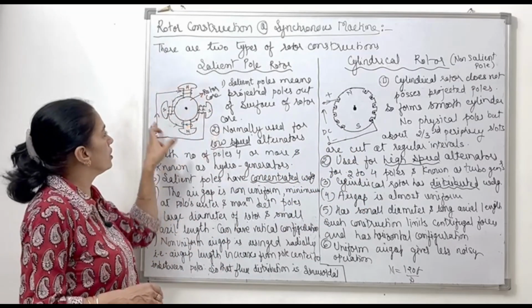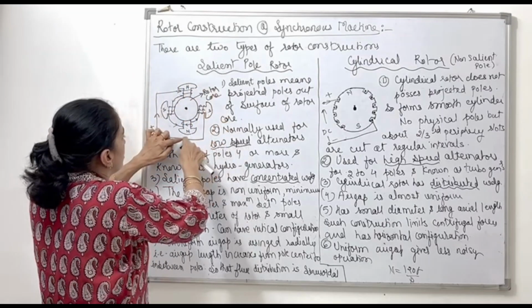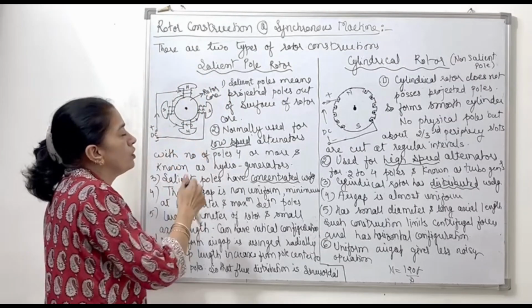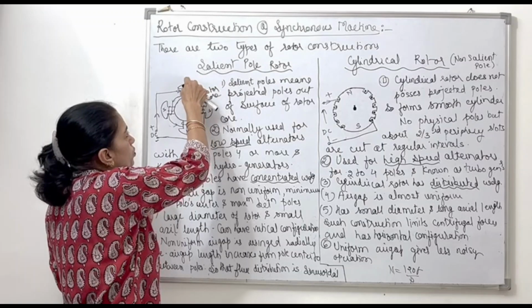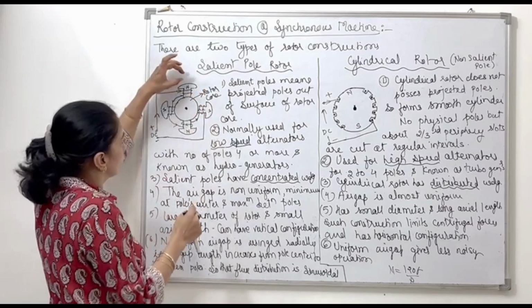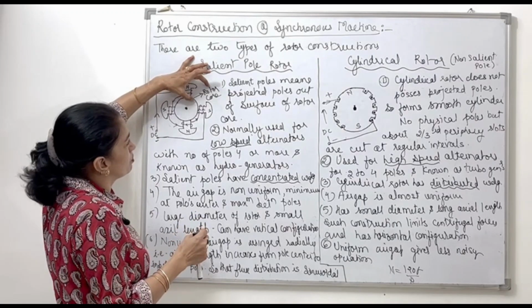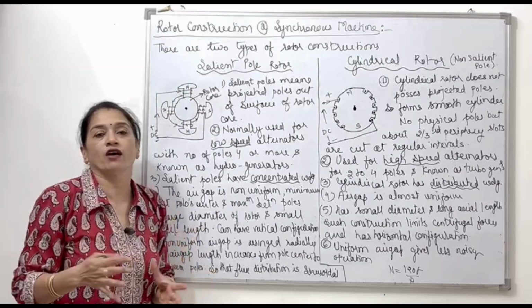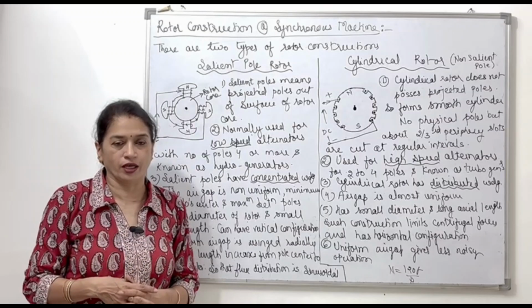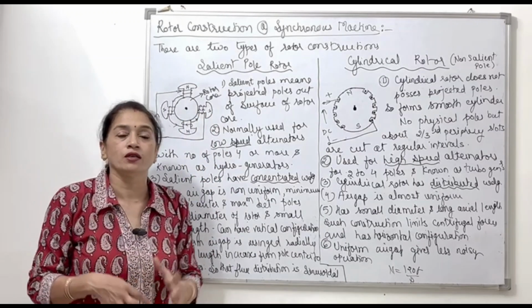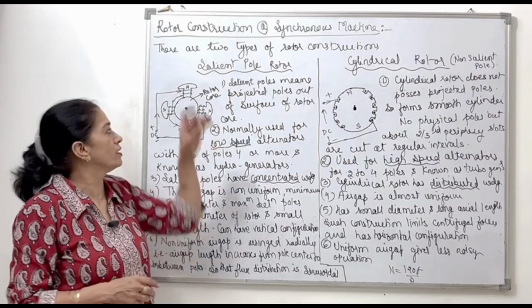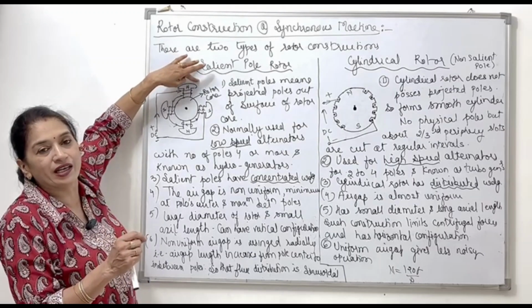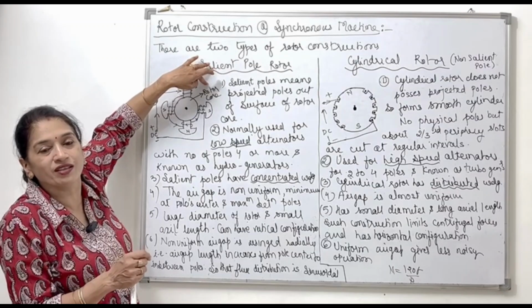Now, one more thing here, the stator would have the periphery like this. So this is the ring type cross section of the stator, you can imagine over here. You can find that in between the stator and the center of the pole tip, we would have some small air gap, and the biggest air gap exists between the stator inner periphery and the space in between the 2 poles. So here we have a non-uniform kind of air gap. We try to make it radially increasing. That means here at the center of the pole we keep the lowest air gap, and radially that air gap is increasing till in between the poles.